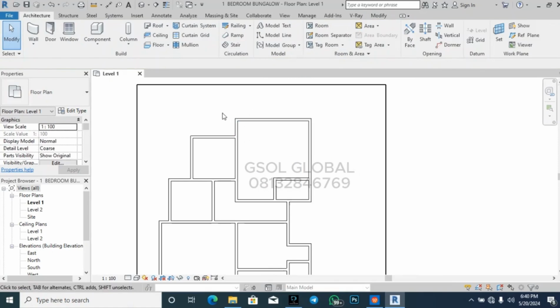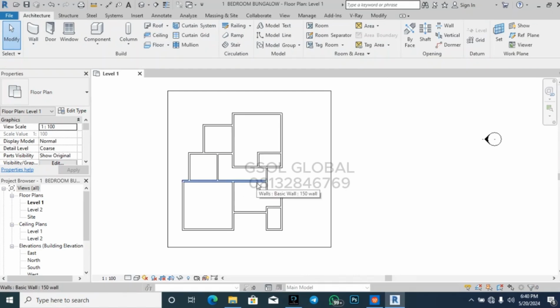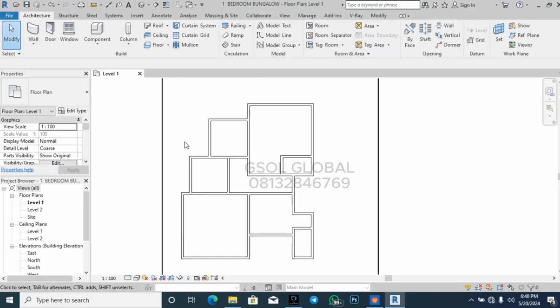So the next thing after you've created all the space required is to start adding some important details so that even you will not get confused as time goes on. What are those details? Details like your dash line representing the beams, where you have the beam in the building. That's direct beam. So you have the direct beam in the porch and in this porch. So I'll have one here, one here, and I also have one here. So let's go ahead and do that.